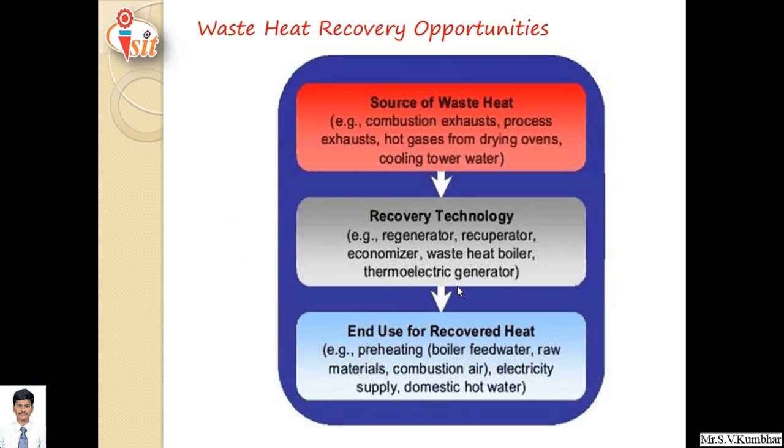Now coming back to waste heat recovery opportunity. This is the last point of the second unit. First of all, we have to identify sources of waste heat, that is combustion exhaust, process exhaust, hot gases from the drying oven, cooling tower water. These are the different sources of waste heat.